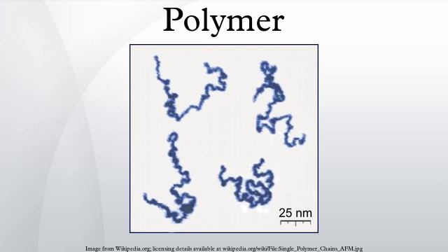Molecules can be thought of as being surrounded by a cloud of negative electrons. As two polymer chains approach, their electron clouds repel one another. This has the effect of lowering the electron density on one side of a polymer chain, creating a slight positive dipole on this side. This charge is enough to attract the second polymer chain. Van der Waals forces are quite weak, however, so polyethylene can have a lower melting temperature compared to other polymers.